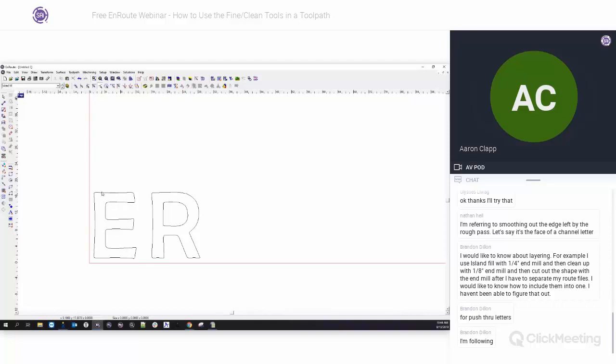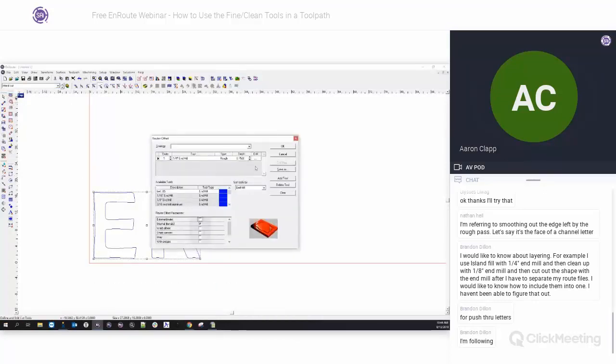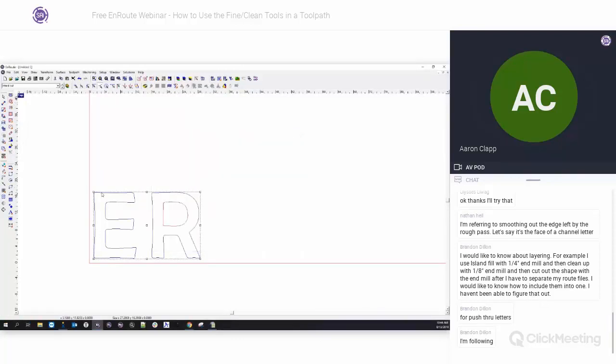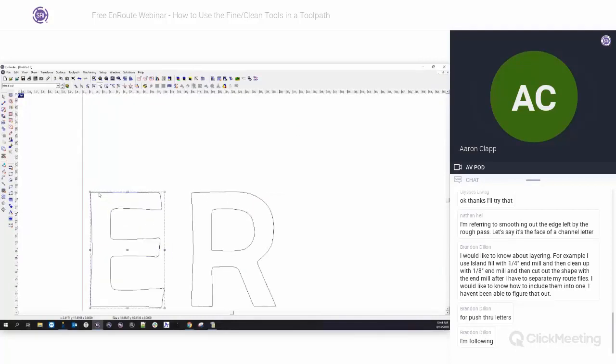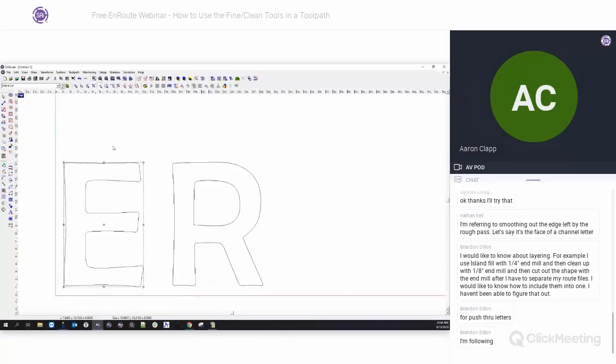if you're using the same geometry, that doesn't make a whole lot of sense to do, because the problem that you run into is that if I apply a routing offset to this letter here, and then I use the same geometry, and the only thing I do differently is apply a smaller bit to it, the size of the letter hasn't changed at all. So the second bit is actually just going to cut in the air. You'd actually have to make the letters smaller for one of the files, so that you could cut that clean.